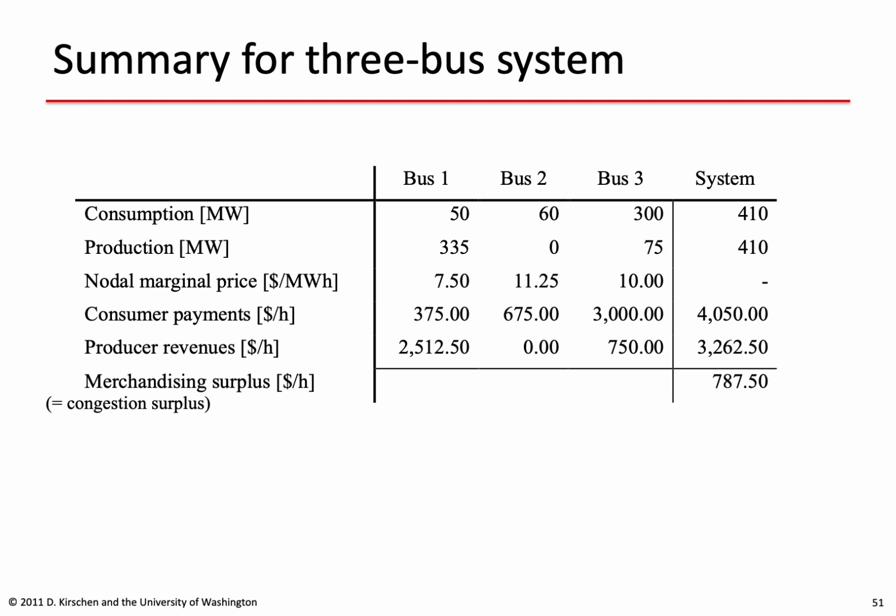That's given by the price at the node times the consumption at that node. And the next line is the producers' revenues, which is given by the amount that these producers produce times the nodal price that they are getting for their production. So there is no producer revenue at bus 2 because generator C is not producing anything.